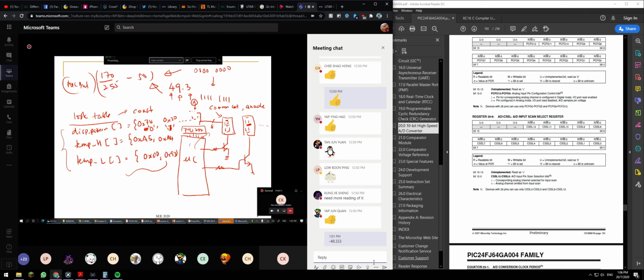It's up to you. But remember, if you are a professional designer, you are looking for a proper design, so you will use this rather than this. If you use this, power consumption is very high and you also take up a lot of memory, because a lot of calculation is going on. So again, this is not recommended. People prefer using a lookup table.